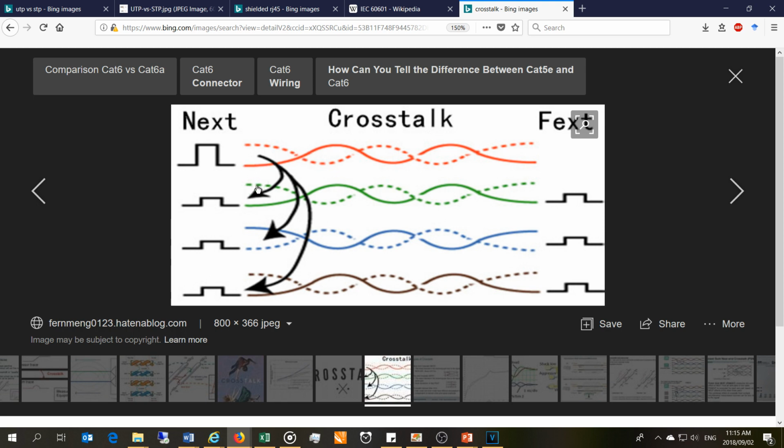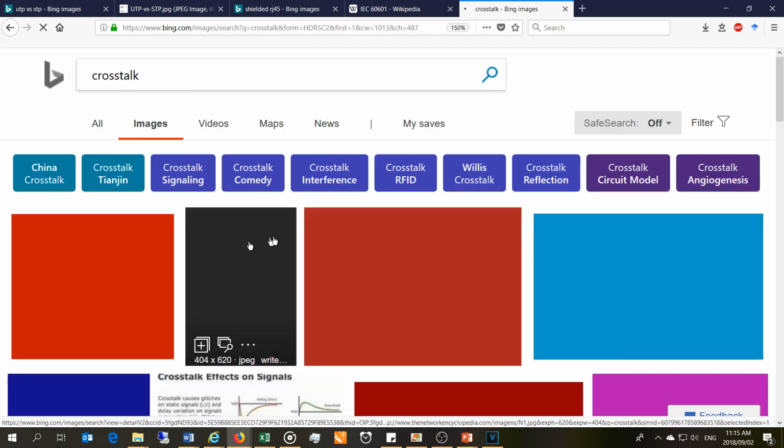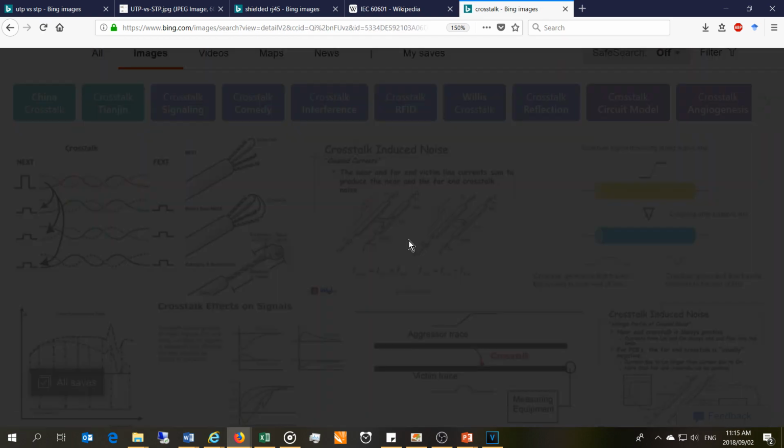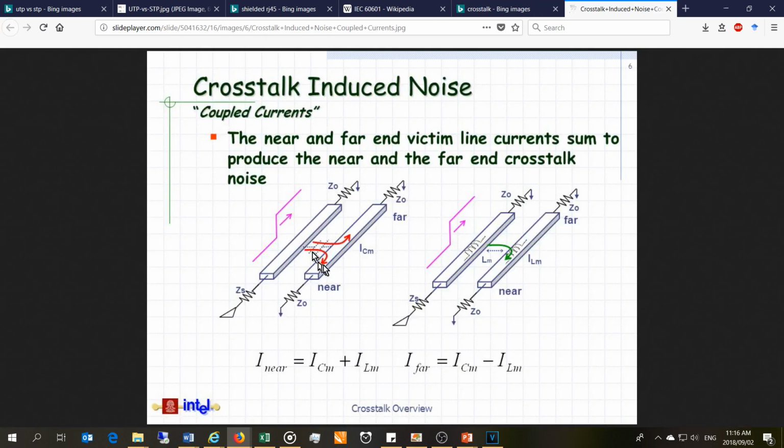So it's not exactly the same as what is traveling in the original conductor. So it influences the cables nearby. And when we twist the pairs, by twisting it, we kind of counteract that. So here we go back to this conductor. And if these were twisted, if we could twist these around, well, the magnetic field that occurs here would then be cancelled out because I have twisted the cable 180 degrees. So this is one of the reasons for the twisting of the cable.